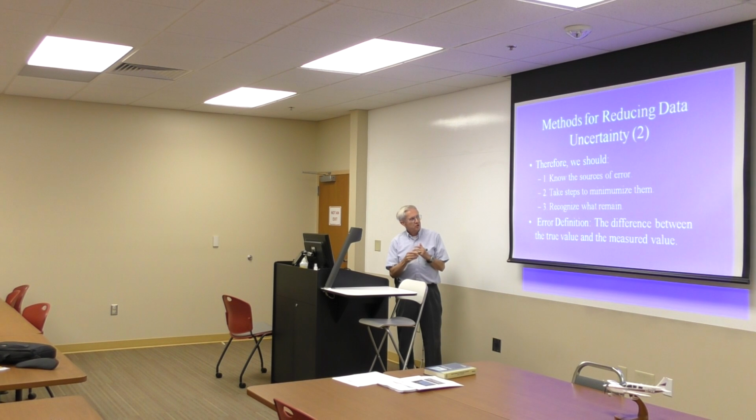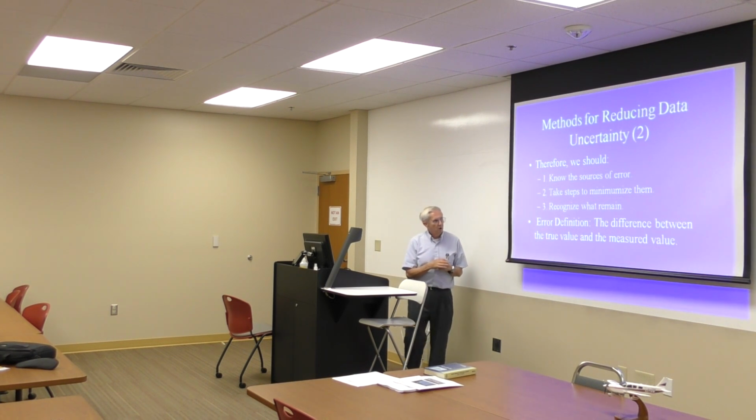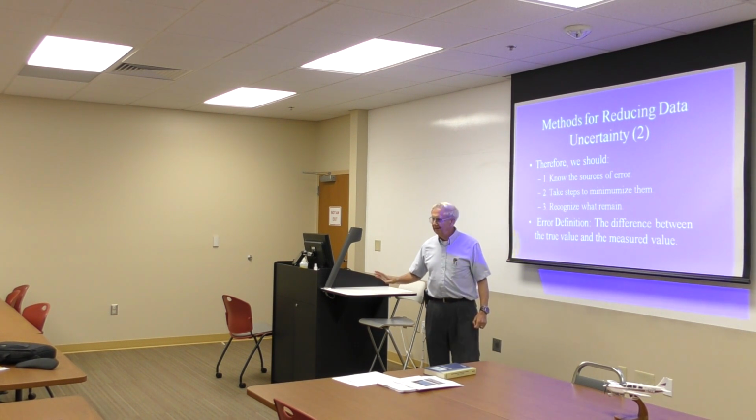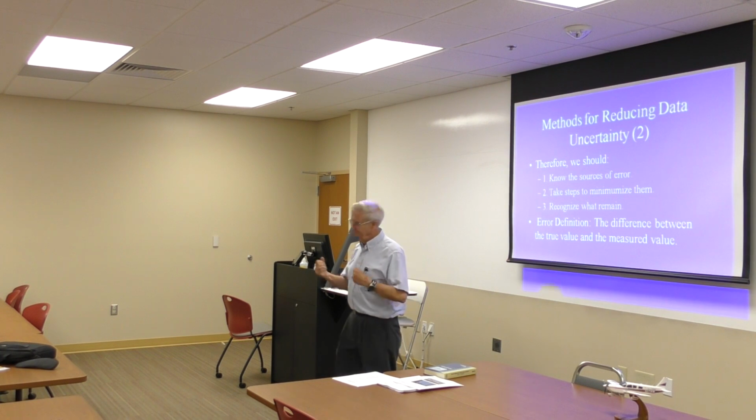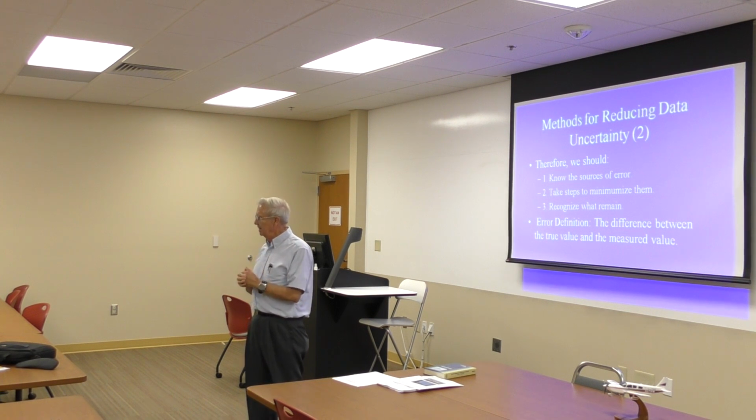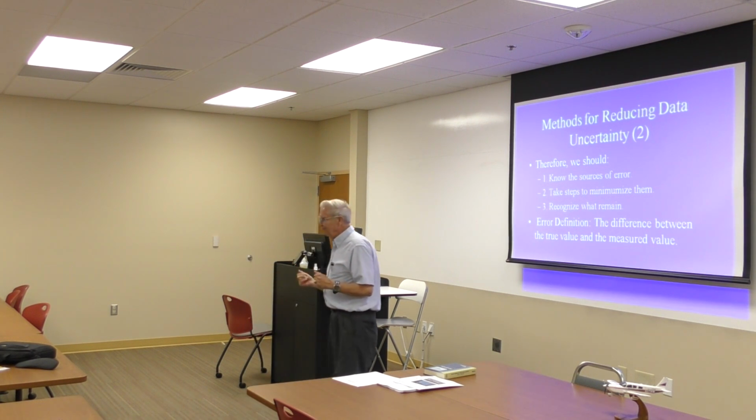Well, we ought to know where the errors come from. We ought to do all we can to minimize them, and then recognize what remains. And by that, I've had folks who work for me and students come to me with flight test data with 4 decimal places. Ain't gonna happen, folks. You're lucky if the first one to the left of the decimal point is valid, okay? That's the kind of thing you have to recognize. You know, we're not gonna get 4,